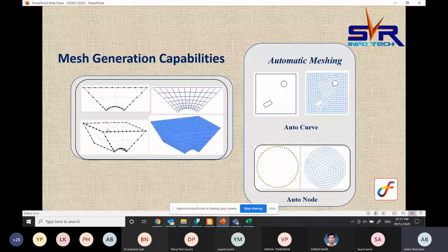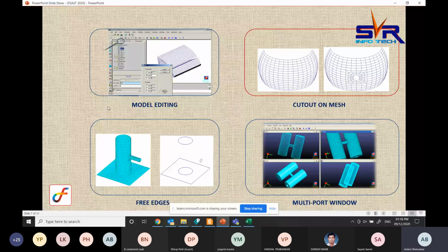Map meshing capability is similar to HyperMesh, where you can simply use your left click to increase the mesh density, right click to decrease the mesh density, and you can create the manual mesh, and then you can extrude. Then you can extrude, glide, and sweep. Other transformation tools can be used on these 2D elements. So a versatile tool for meshing, I'll say. Once we go to our GUI, I'll show you what exactly the capabilities are.